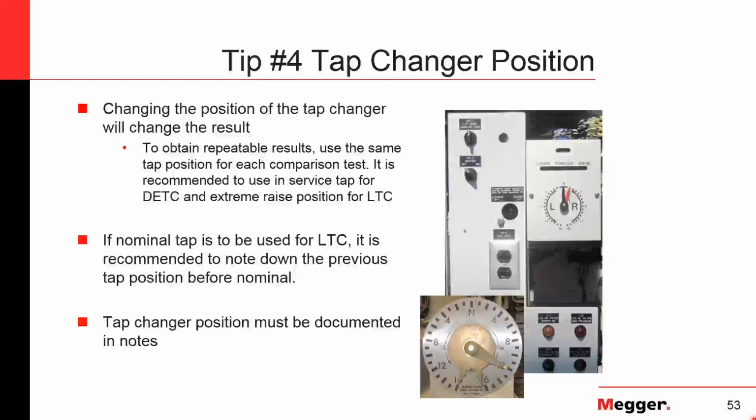But you'll see it also overlay into the low frequency range, and it could overlay into the high frequency range as well. And then as you get to the high frequency range, as I said, the windings overlap up there too, but that could also be a problem with a bushing connection or a connection on your tap changer.